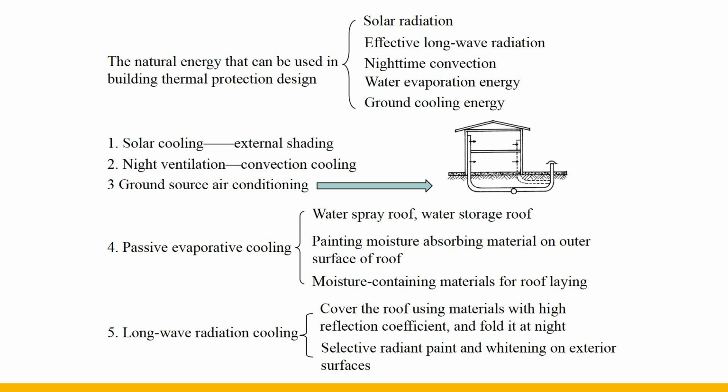Passive evaporative cooling is a method of using the latent heat of evaporation of water to reduce the temperature of the exterior surface of the building, thereby improving the indoor thermal environment. It mainly uses water storage roofs, water spraying roofs, or paints hygroscopic material on the outer surface of the building, and lays porous moisture-containing material on the roof.